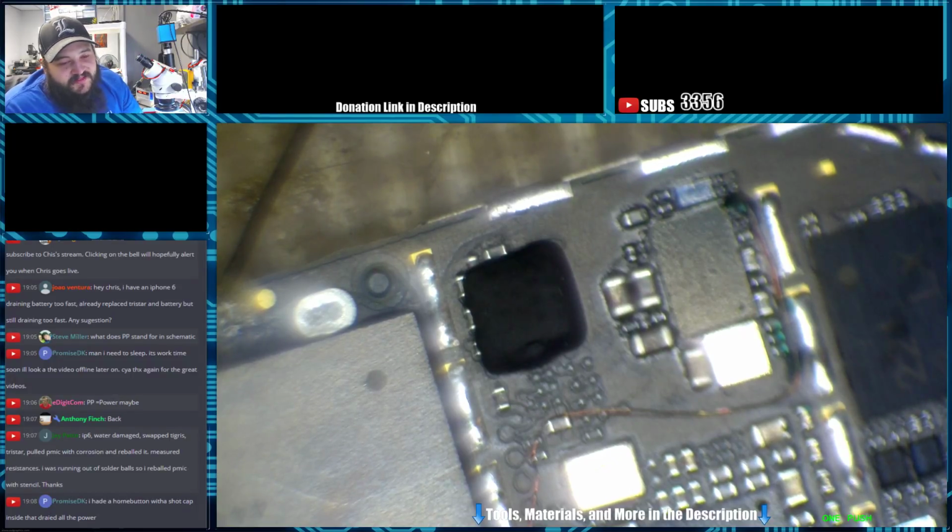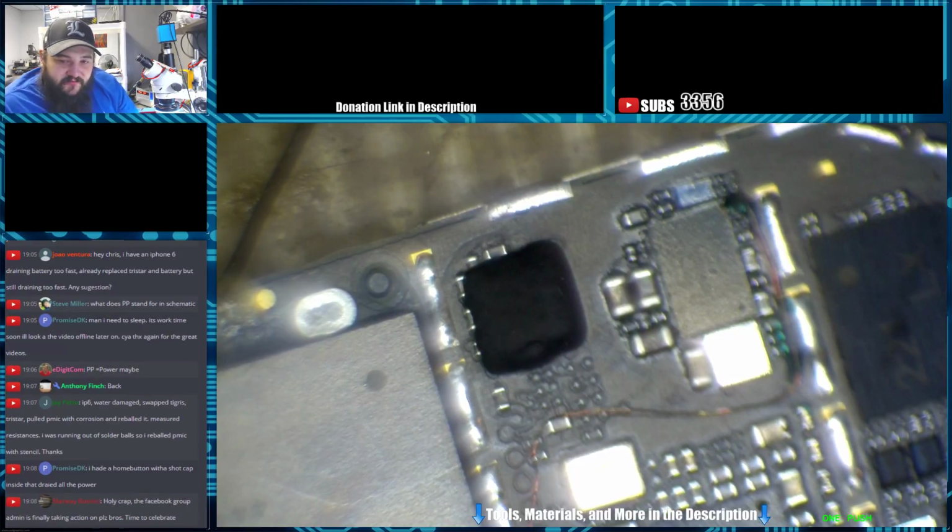The best thing to do with voltage shorts or amp draws is disconnect everything you don't need. Just have a brand new screen hooked up with a good battery and nothing else, and see what it does. Then start plugging things back in until you find it.